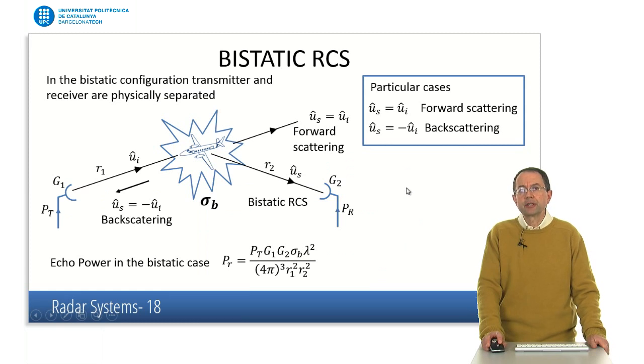Also, on radar cross-section, there are special situations, like, for example, this one. Normally, most radars are monostatic. This means the radar transmitting and receiving antennas are the same or are placed almost at the same position. But that's not necessarily the case in all radars. Some special radars are bistatic, which means the transmitting and receiving antennas are separated at different positions.